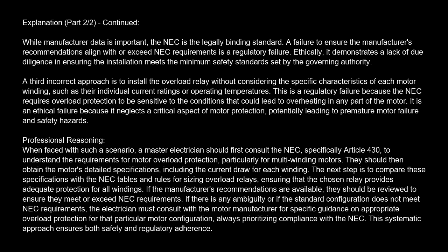Professional reasoning. When faced with such a scenario, a master electrician should first consult the NEC, specifically Article 430, to understand the requirements for motor overload protection, particularly for multi-winding motors. They should then obtain the motor's detailed specifications, including the current draw for each winding. The next step is to compare these specifications with the NEC tables and rules for sizing overload relays, ensuring that the chosen relay provides adequate protection for all windings.